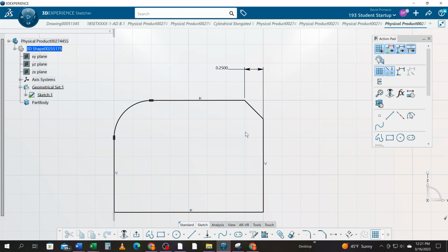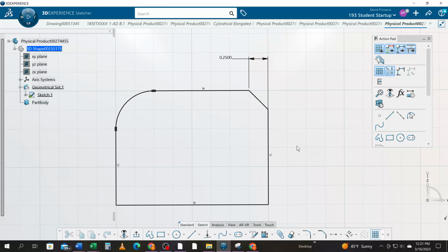So if you have this part and you're working out in the shop and you just want to lop off this to make a chamfer edge, you want to start with that raw material, measure over ¼ inch. You mark that on your chop saw, and then you just chop it at a 45-degree angle. And that's how they do it, because trying to figure out that hypotenuse is going to be almost impossible, trying to figure out where that point is without doing a bunch of geometry. So that is the best technique for that.